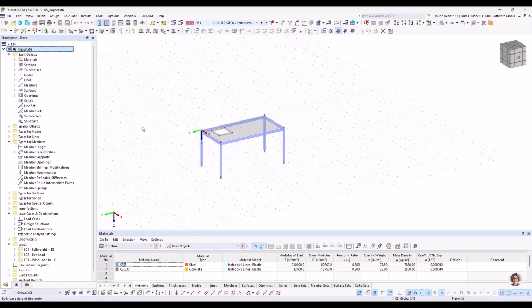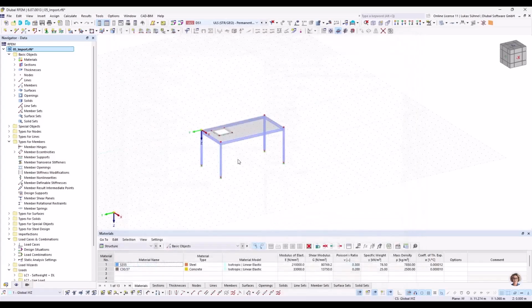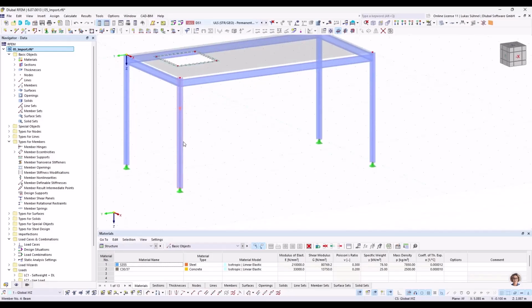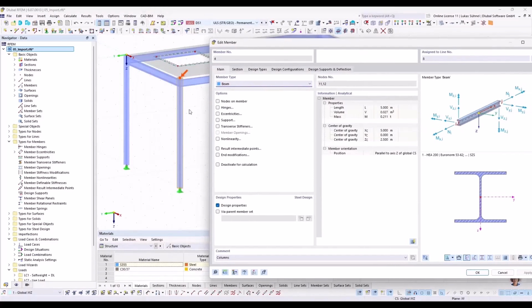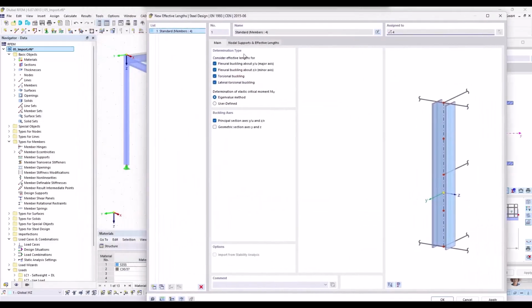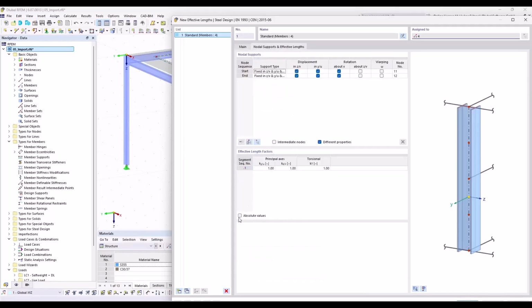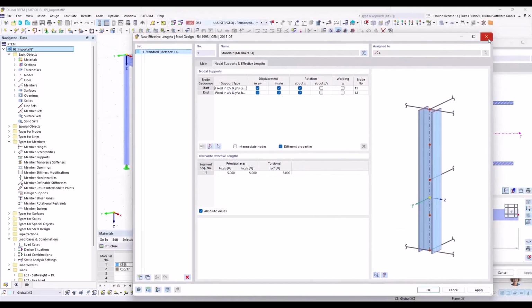Let's imagine we want to run the steel design in RFEM afterwards. For the steel design, we have to define additional properties. What's the buckling length of the column? That's a property inside the member dialog, design types. Here I can say use or perform flexural buckling, lateral torsional buckling, and all these checks. And then use as a buckling length, maybe length XYZ, 5 meters. These inputs are, let's say, relatively complex for a Grasshopper component.